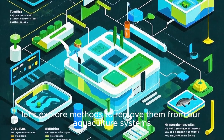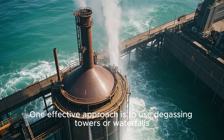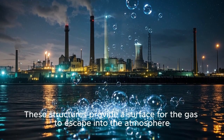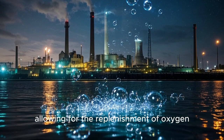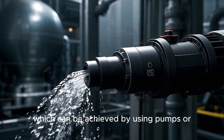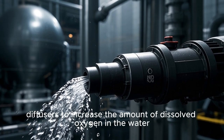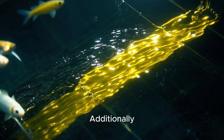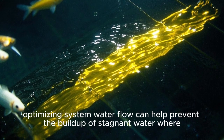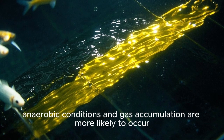from our aquaculture systems. One effective approach is to use degassing towers or waterfalls. These structures provide a surface for the gas to escape into the atmosphere, allowing for the replenishment of oxygen. Another method is aeration, which can be achieved by using pumps or diffusers to increase the amount of dissolved oxygen in the water. Additionally, optimizing system water flow can help prevent the buildup of stagnant water, where anaerobic conditions and gas accumulation are more likely to occur.